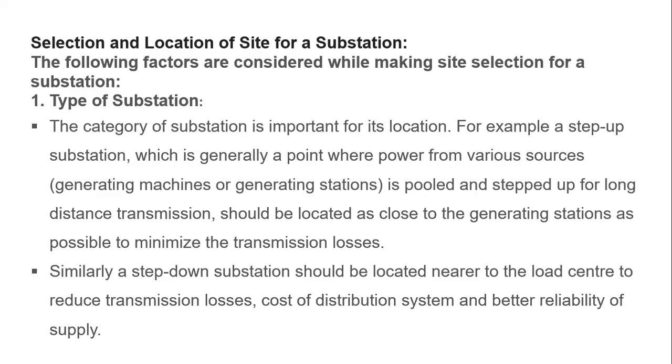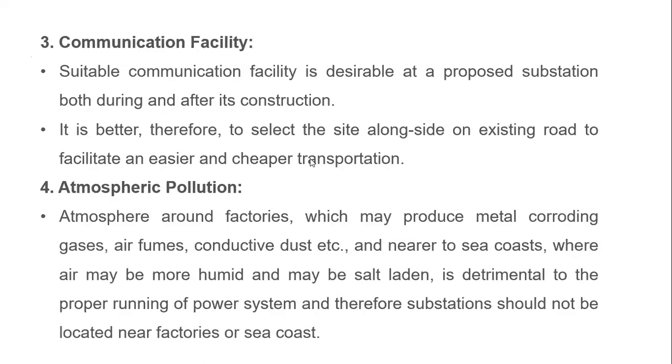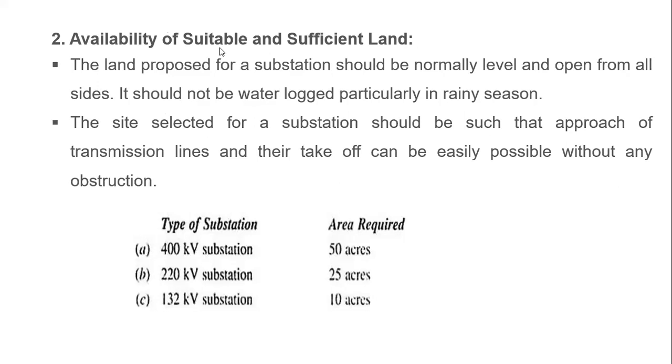It should help to minimize the number of customers affected by the service outages. These are all the considerations for the selection of the site for substations. Mainly we are observing which type of substation will be located, for example, a step up substation or a step down substation, and also the availability of suitable and sufficient land for future extension and forecasting purposes.